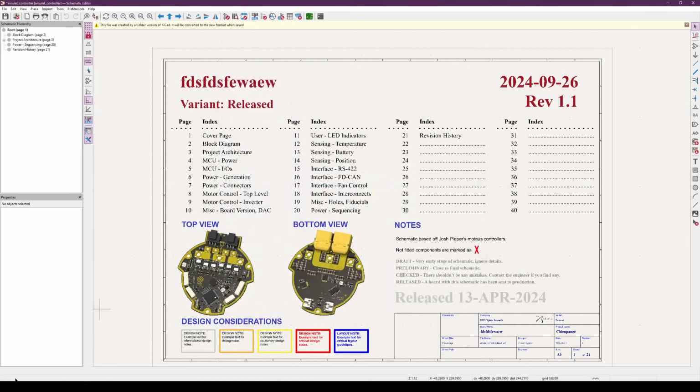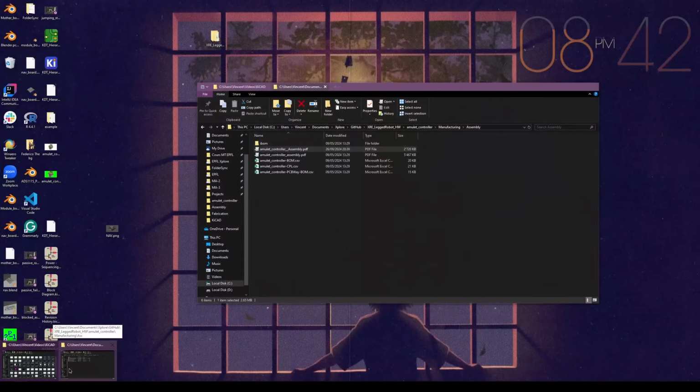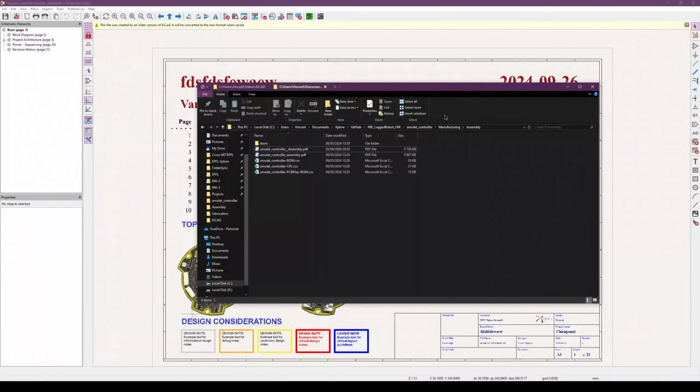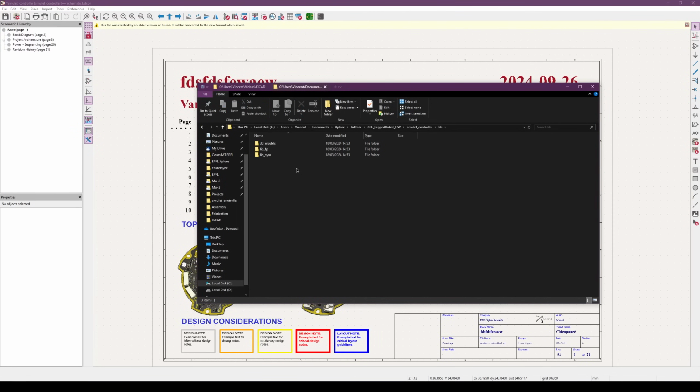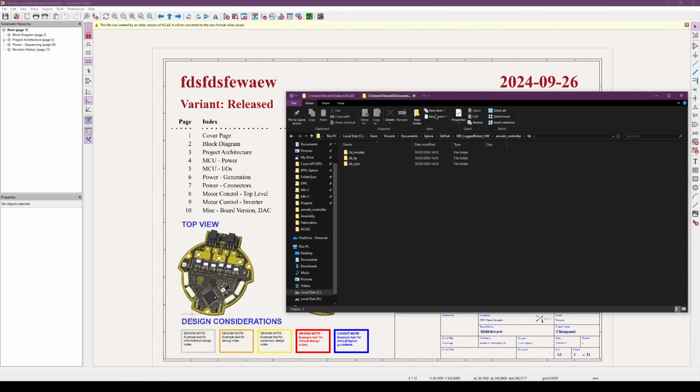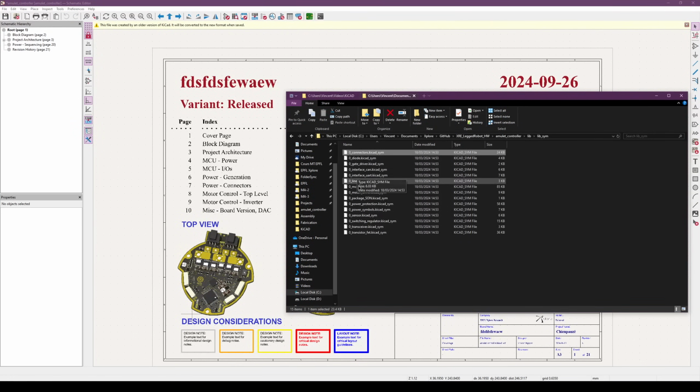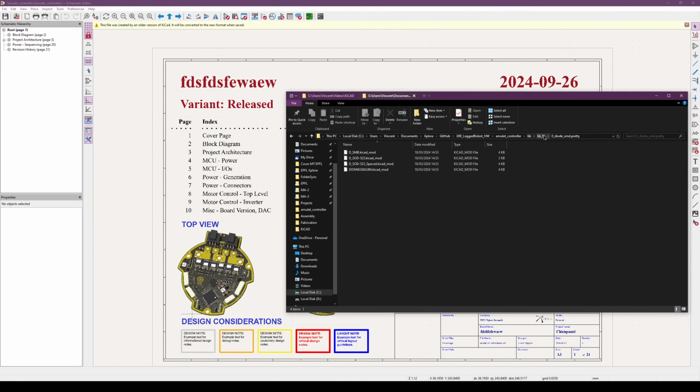So why local? This is because this allows us to share the project a lot more easily than if it was a global. So I usually just have a lib folder here, and I then have two subfolders, one for the symbols, where I set all of my libraries for the symbols, and then I mirror the names with the footprints, and in each footprint library, I add all of my footprints.